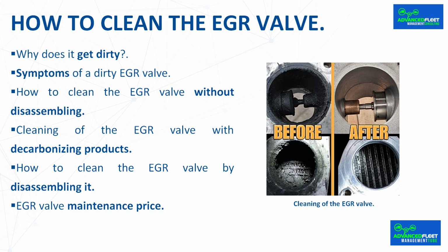How to clean the EGR valve without disassembling? To clean the EGR valve without disassembling anything, these techniques can be used. High-speed driving. A simple way to try to clean the EGR valve is to drive at high speed for several minutes. The increased temperature and gas flow can help burn off some of the accumulated soot.